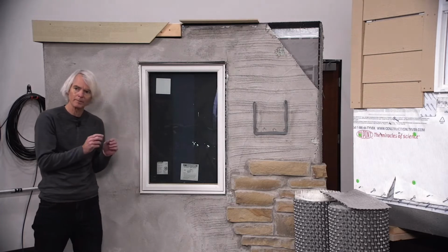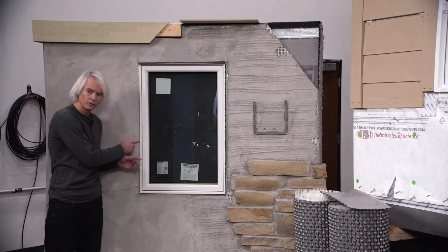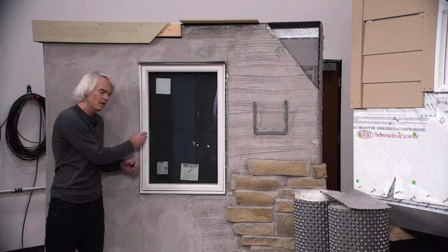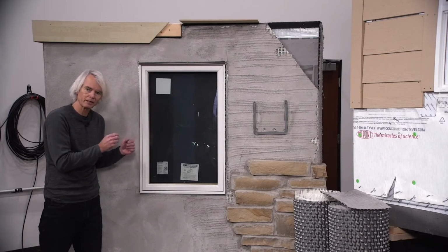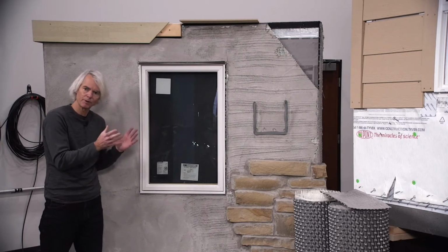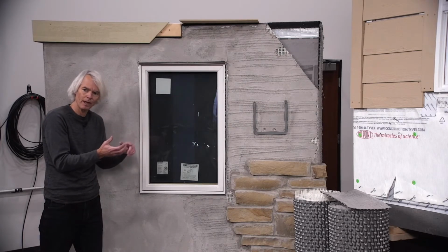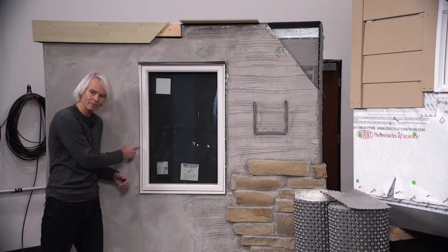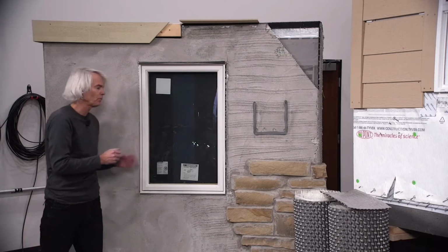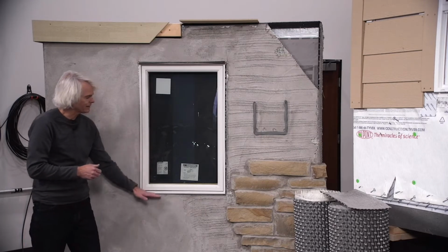The reason behind that is durability of the building. We talk about pulling off a detail with the best durability. The window may, through thermal cycling, expand or contract, and so we want to allow for some differential movement of either the building or that window. So that gap is a critical thing there, so we don't either crack the stucco or cause damage to the window. That's been done on the sides and the bottom.